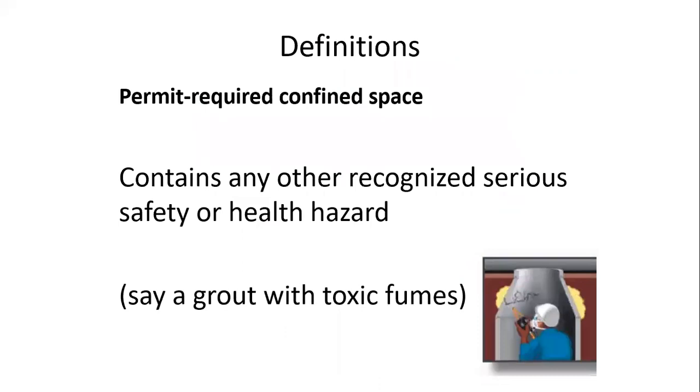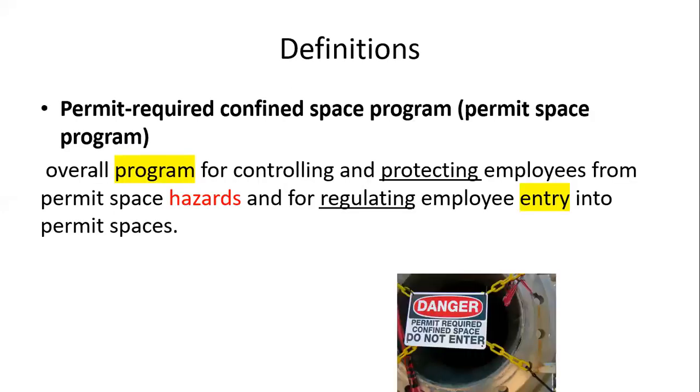Say you had grouting going on and there were toxic fumes. Even if everything else was all right, and it would normally be considered a permit required confined space, because of those toxic fumes, you would consider it a toxic space.